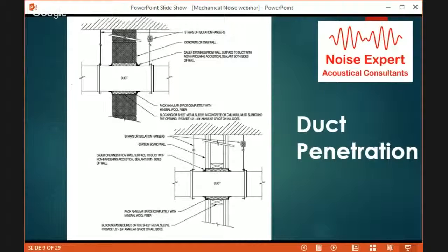If you have a light on in that mechanical room and you're in the other room and you can see light on the other side, there's a poor seal and there's going to be a noise issue. You can have a pretty large barrier, and a small opening will dramatically reduce the sound transmission class, or the amount of noise that it blocks. So small openings can add up and hurt. So you have to be real careful.